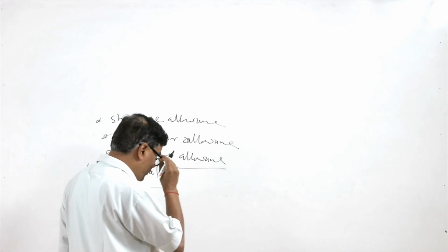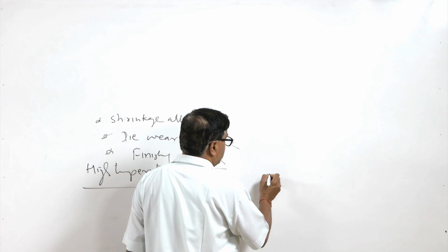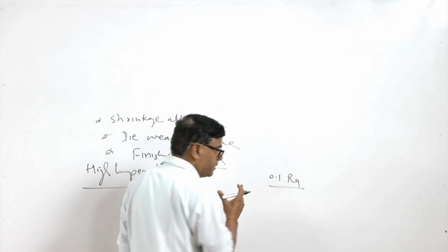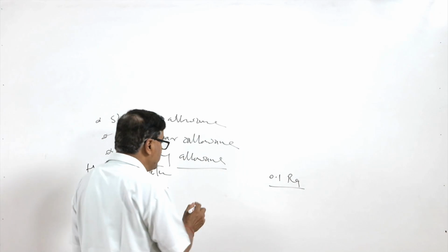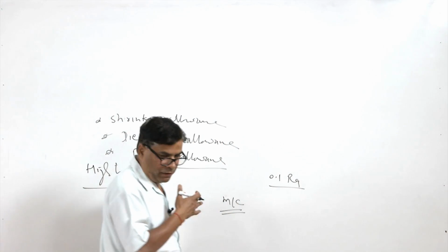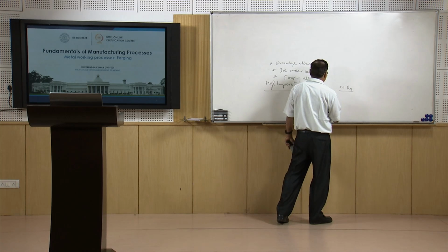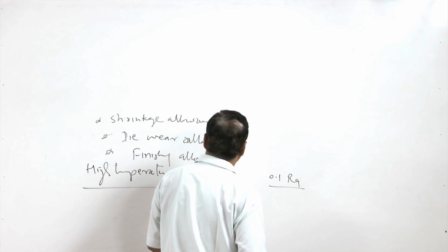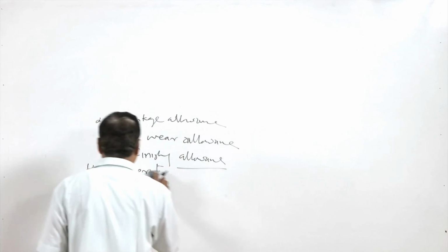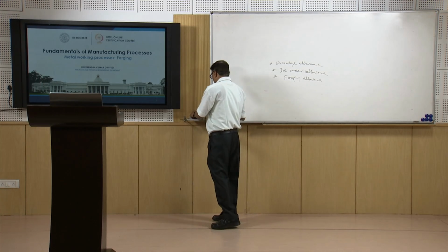If you want to have a very good surface finish, like 0.1 Ra, which of course cannot be achieved through metal working processes, we need to machine the surfaces. For machining the components, we need to have the material. So, additional material is provided for the machining purpose, so that the desired finish can be achieved, by giving the machining allowance. These are the additional features related to forging.